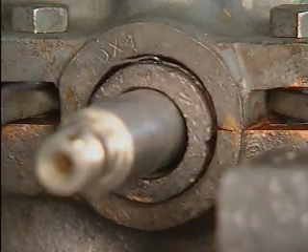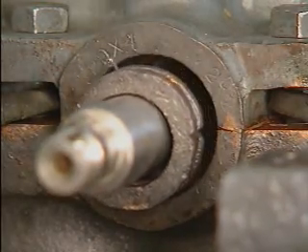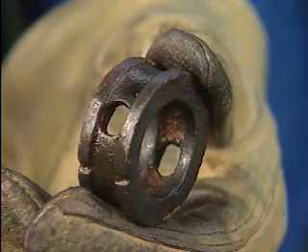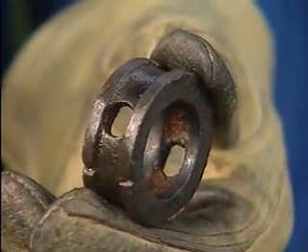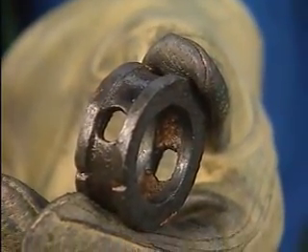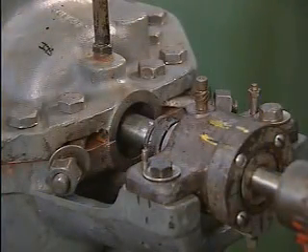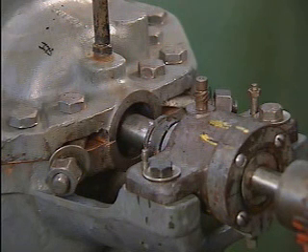He then hooks the wire onto the edge of the lantern ring and carefully slides it out of the stuffing box along the shaft. Many lantern rings, such as this one, are one-piece devices. In our example, the lantern ring can easily be removed from the shaft. However, in many applications, it's not possible to remove the lantern ring completely. In such cases, the lantern ring is usually tied out of the way.